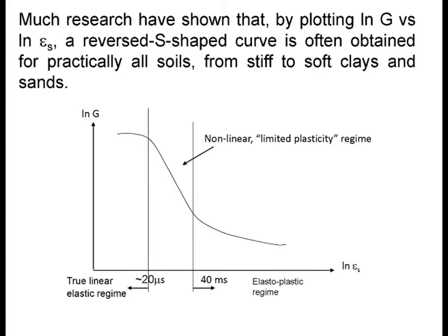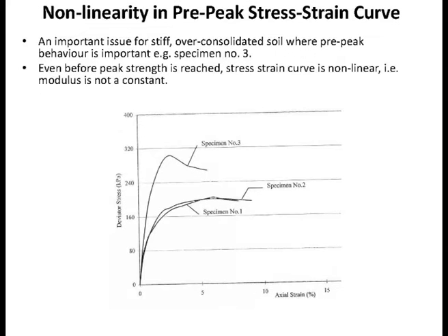A model like hyperbolic probably gives you a better chance of doing that. In that region it is elastic, but you are able to model that turnaround. And this high value here is associated with the fact that right at the beginning, the tangent stiffness is very, very high. The tangent modulus is very high. And then as you go up, the tangent modulus will drop. So the idea is that you need to model this reasonably well.